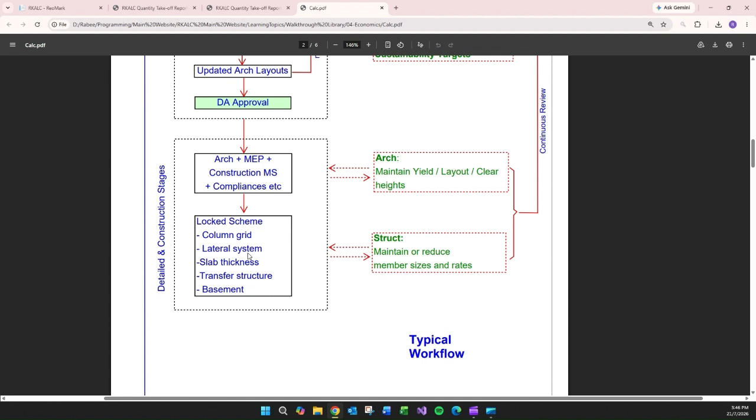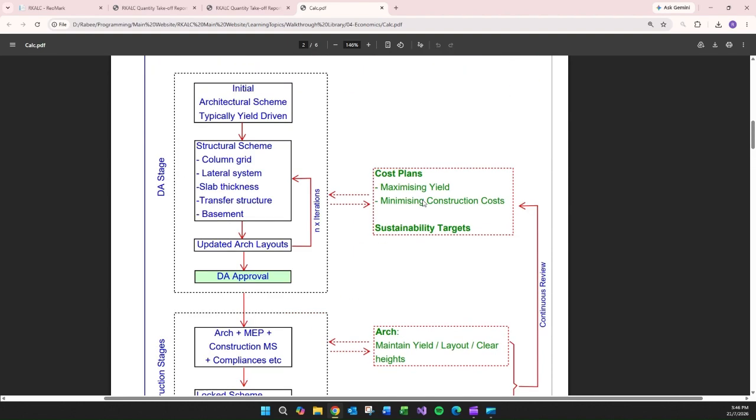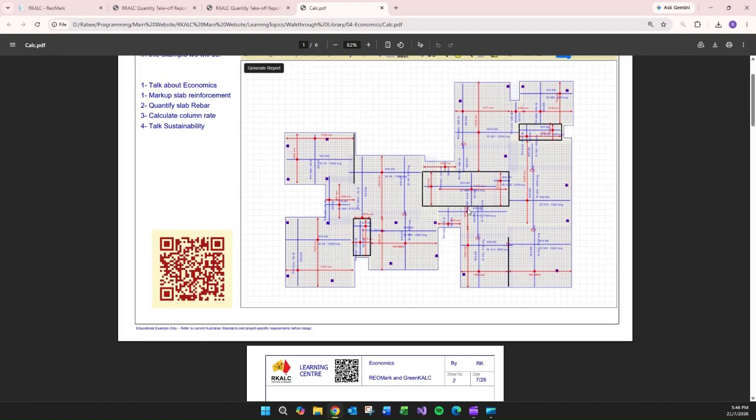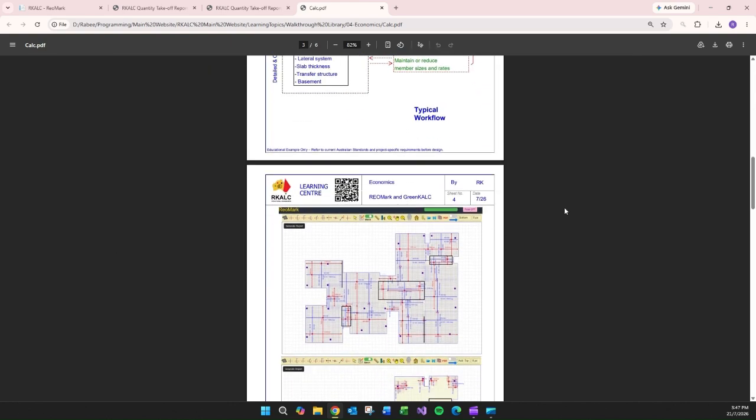If you commit to those numbers without doing proper math, there will be a problem, because each project has its own merits. For example, end spans are too many, or the slab system is screaming, or you do not provide a column grid that is appropriate for a PT slab or RC slab, where the column grid is an important thing.